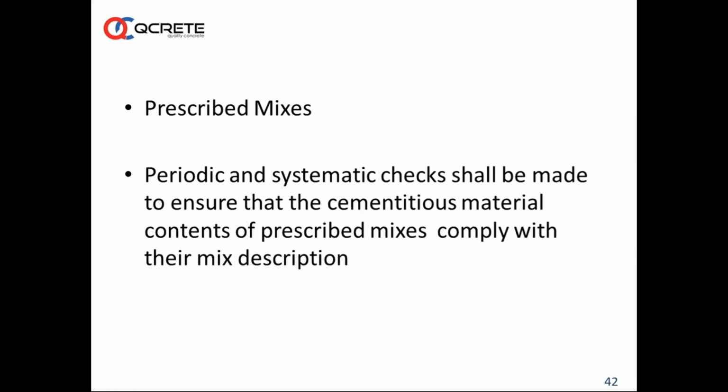But unfortunately, many times it happens that even after prescribing the mix, many of the customers try to put the responsibility of concrete quality onto the producer. This is a very bad practice, I can say. So what is the responsibility in this situation is that anybody who has prescribed the mix can come and check in the ready mix company whether the same mix has been used with the same ingredients, everything same as per the written document or written specification, the written prescribed mix.